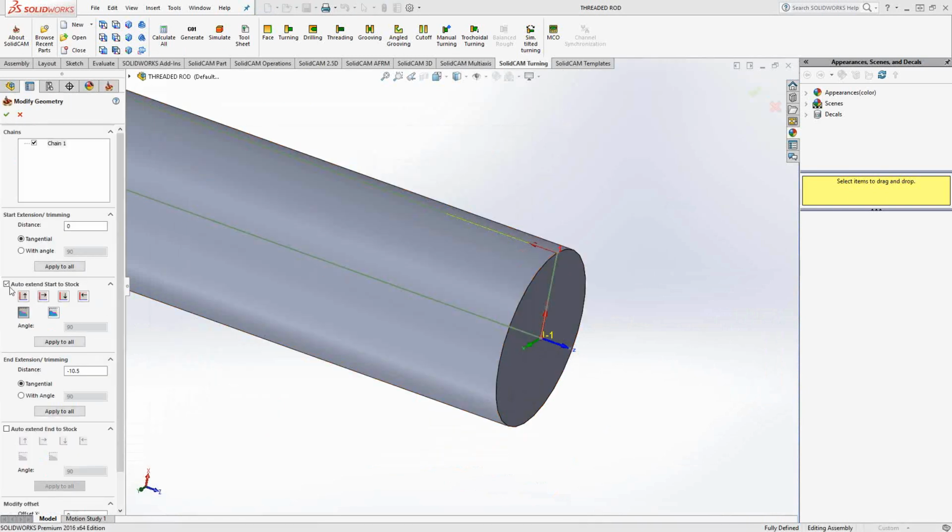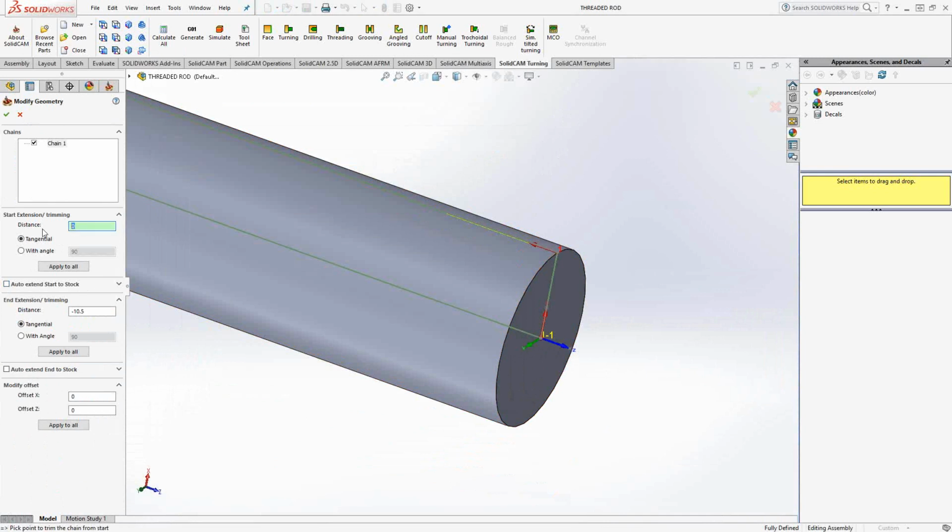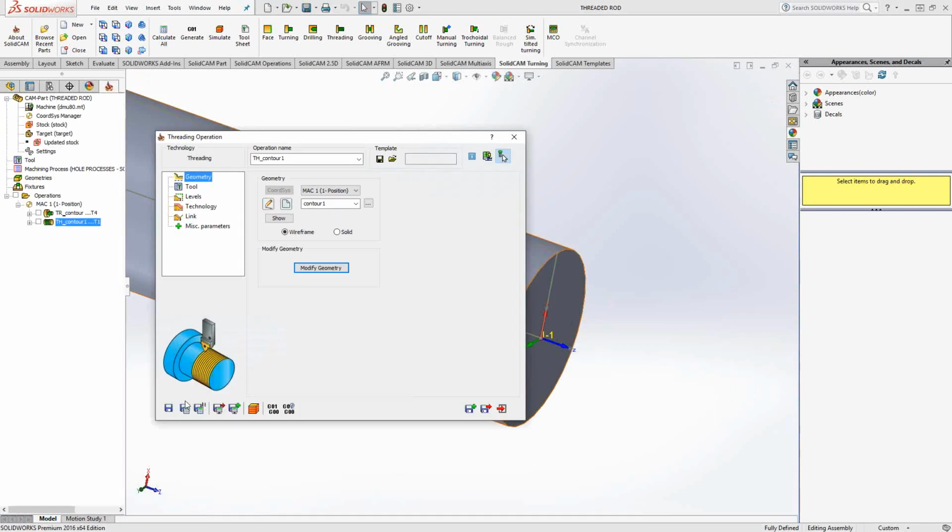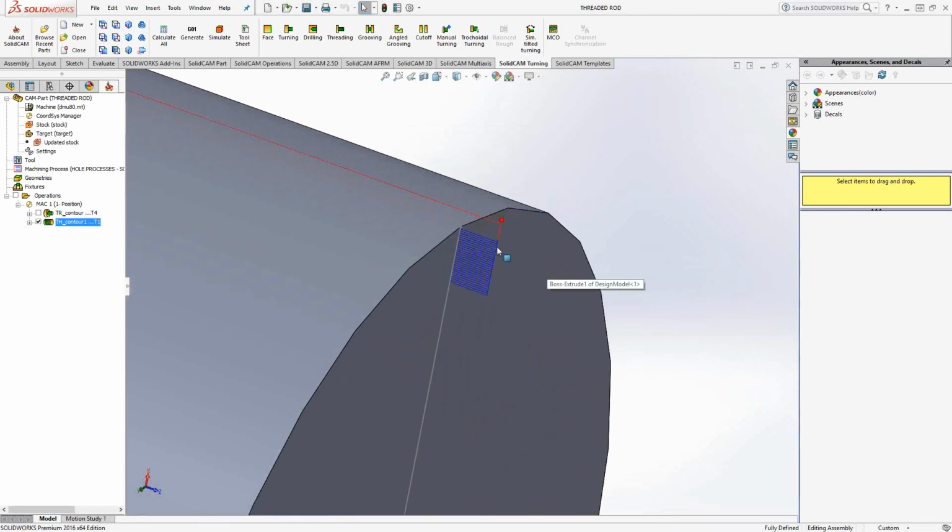And instead of relying on the lead in and lead out, I can actually, on the front side, add a little bit of a lead in myself here. I think that's actually maybe a little easier to control. You can see that it actually extends the toolpath that far.